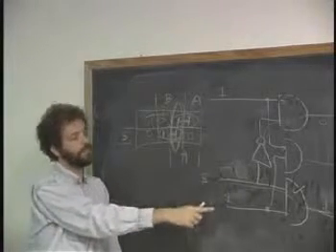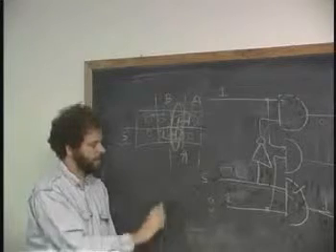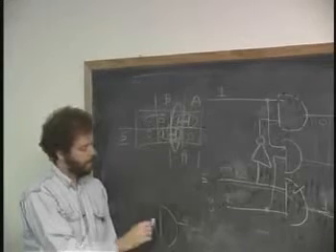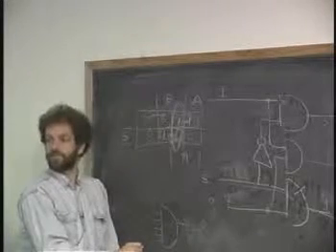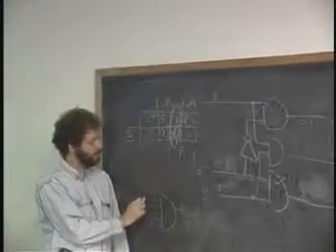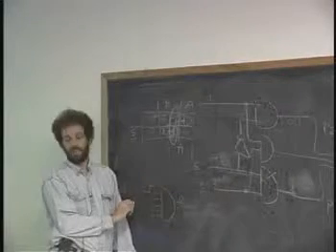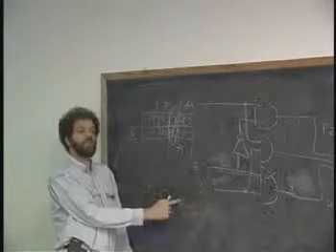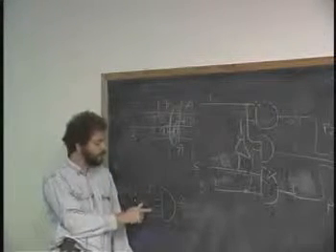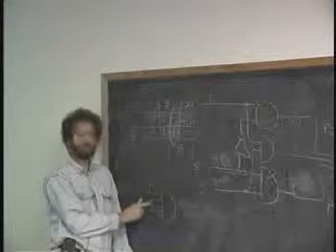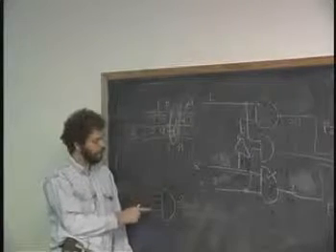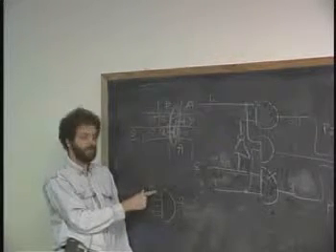So of all of these gates, okay, let me take a typical AND gate. Before, it had a 0. Afterward, it had a 0, correct? And only one of the inputs changed. So these all stayed constant, whatever they were, and one of them changed either from a 0 to a 1 or a 1 to a 0. What must it mean for it to be true that before it was 0 and after it was 0, and one of them changed? It means that at least one of these guys must also be a 0. Right? I don't know about the other ones, but at least one must be 0 both before and after.